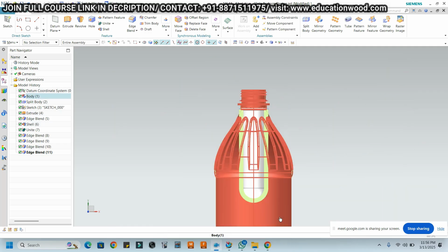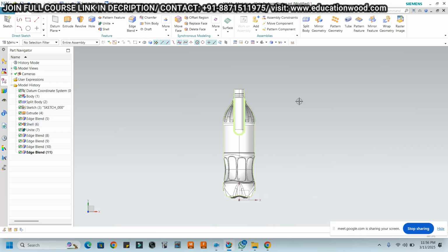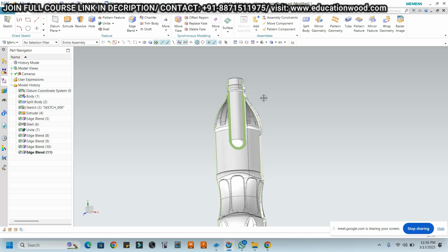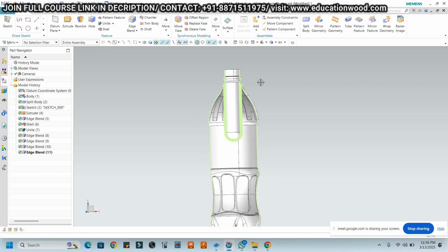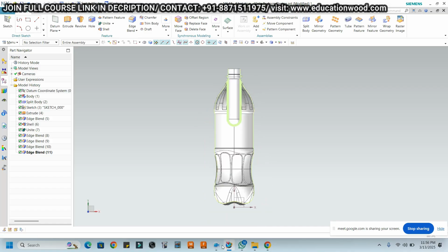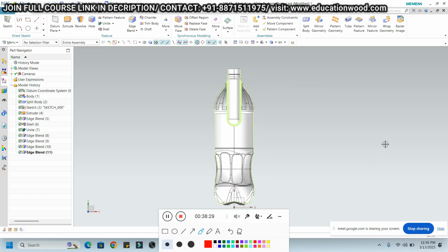Okay, so as we know, if we are working with a PET component, we have to prepare the PET preform, right? If we consider the same thing with PP, then we need to consider the minimum stretch ratio values. For example, let's say PP has 4 to 6. So we cannot go beyond that. If we are working with PP first of all, we can take 4.